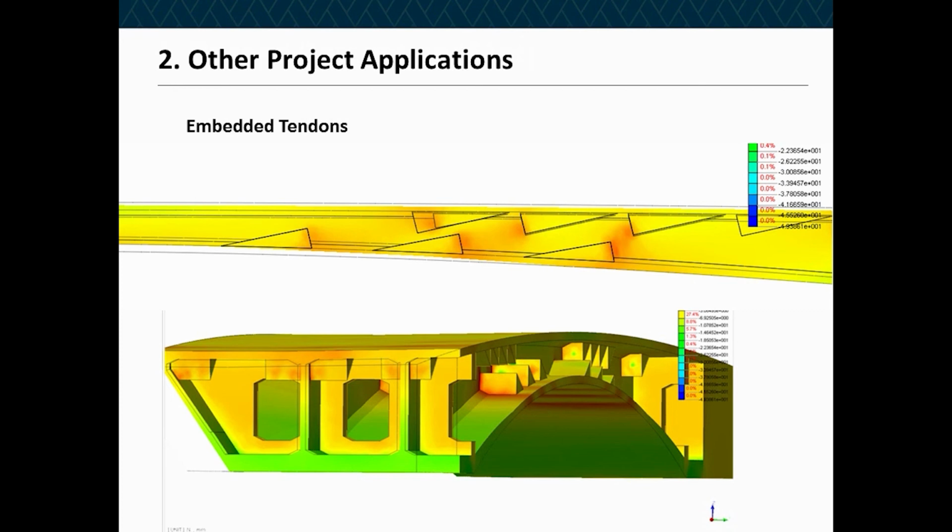So if any of you have particularly shallow bridges at the moment that you're designing with opposing blisters top and bottom, I urge you to consider this in your design, or by all means model it in FEA solids with embedded tendons and see whether you have a problem.